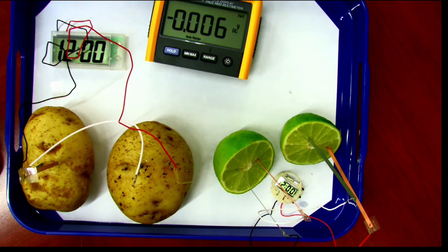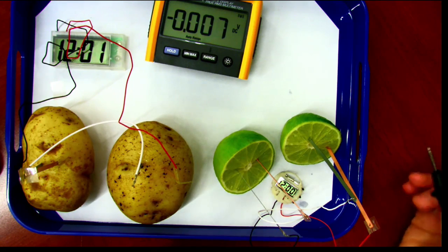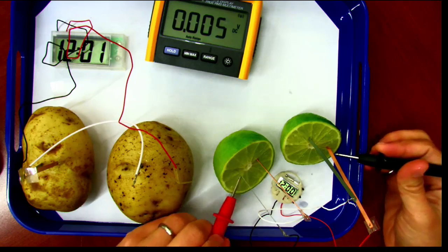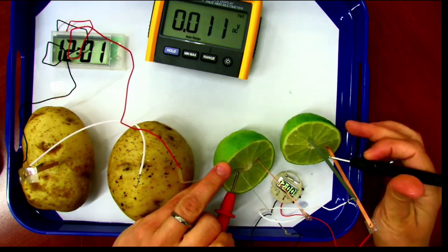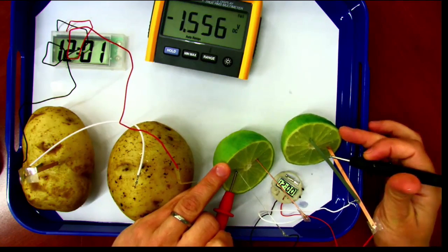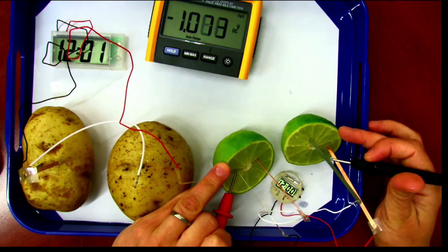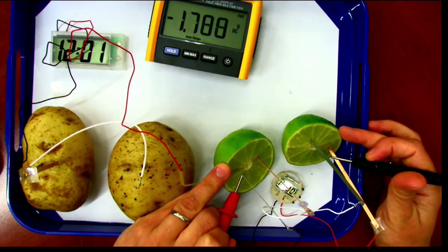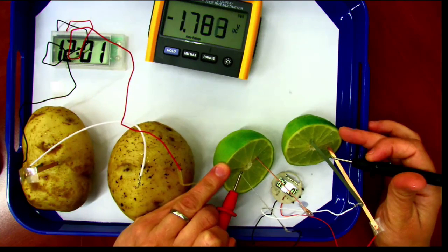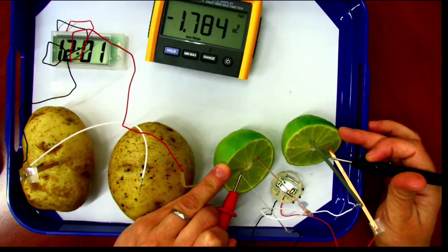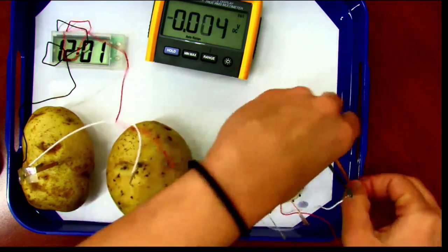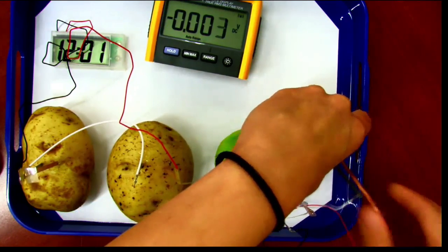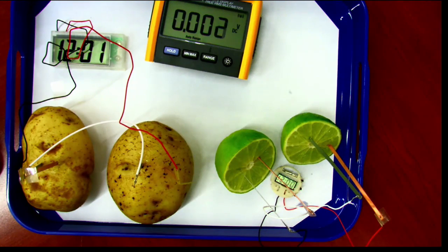So we have an acidic environment, anode cathode pairs. We have 2 limes in series. I don't know what we get out of this. Oh, I touched the right spots. About 1.8 volts. There's different things too. I have these pushed in different depths. There's different areas of electron exchange. And if I brought 2 limes, probably would have had a larger value.